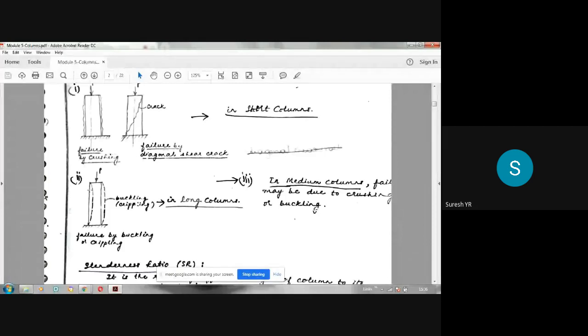In this case, it bends like a beam. Suppose you take a beam, and when you apply load like this, it will bend like this. If you rotate this by 90 degrees, this vertical member becomes a horizontal member and deflection will take place. In the last chapter, we studied deflection. So here, in the case of columns, it buckles. We call it buckling. There we call it deflecting.